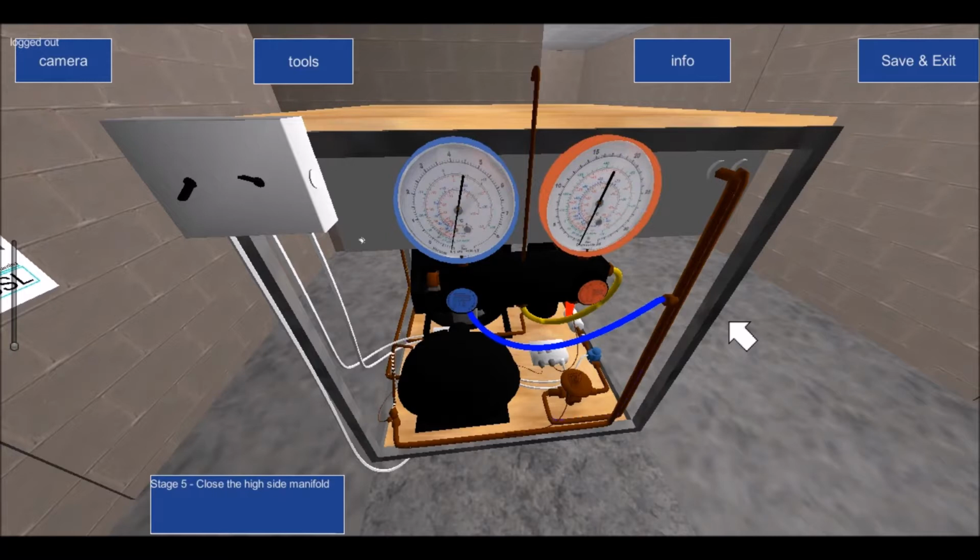Yeah, so effectively what you might find in a lot of scenarios is that the LP switch doesn't exist, maybe, and on other occasions you might find where there is an LP switch that it only really comes into effect as a safety device. So it's only when the refrigerant runs out or escapes from the system because of a human error, then it will cut the compressor to prevent the compressor going into a vacuum and causing further damage.